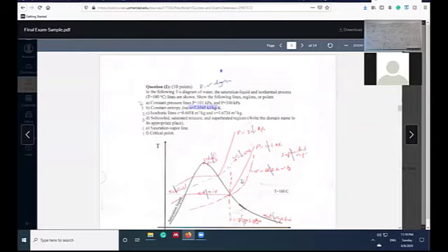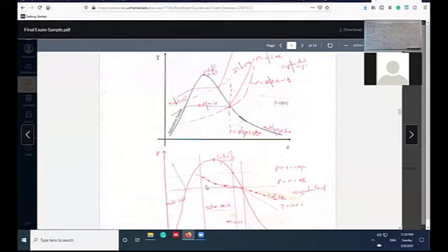For example, if you notice this line, can you see the 1.67? This line passes through this point, 1.67. This one, you see this guy? It passes through the same point, 0.6. So at pressure 300, you will see the vg was 0.6. That's why it touches this point. If you notice also S equals 7.35, guys, are you following me? It's exactly equal to sg at P equals 101. So usually this point is important, usually the saturated vapor line, but also the saturated liquid line. You need to see whether it's here or there. In TS, it's vertical. In PV, it's slanted like this.